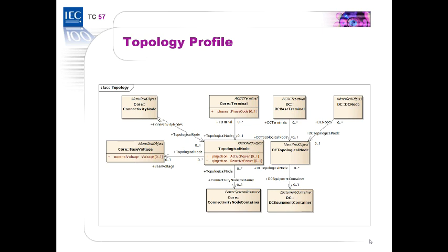And you may ask, why didn't we use the same terminal that we are using on the AC side? And the reason for this is the UML model is nice when you want to check the validity on data. And it's clearly invalid to mix and match HVDC and AC equipment on the same topological nodes and connectivity nodes. That just doesn't work. So by doing the model this way, to have separate terminals and connectivity nodes for the AC and the DC side, that makes it possible for a validator to discover when you have made illegal connections in your data.